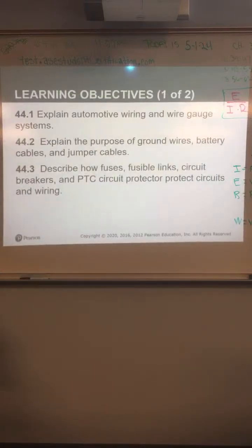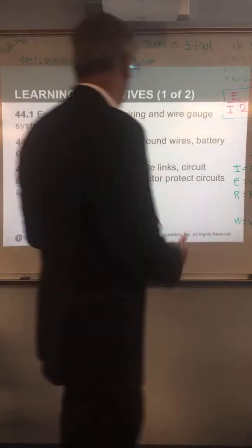Also brought in a test light. Everybody's seen test lights before? Okay. This is your alligator clip, goes on your ground if you're checking for power, right? And this is your probe, poke whatever you want to look for power. Don't pierce a wire, okay? If you're looking for voltage in a wire, go to the connector, touch the metal part of it, okay? We'll do that later too.